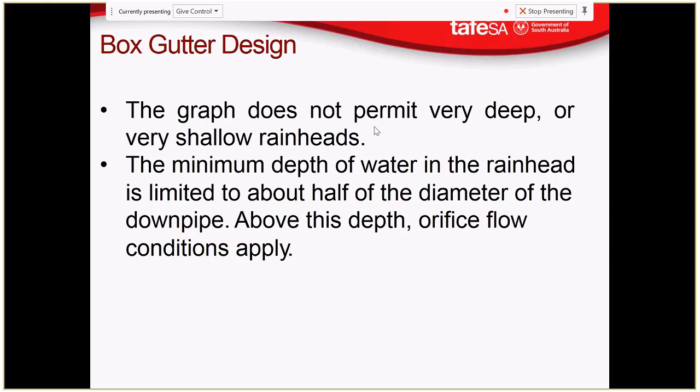So yeah, I guess I won't take you through all of that because we have online calculators. Some of this stuff is becoming superfluous. However, I will say that when you do it through the code or online, it'll give you a size of rain head. It'll say 275 millimeters deep, 150 millimeters wide by 300 or so.